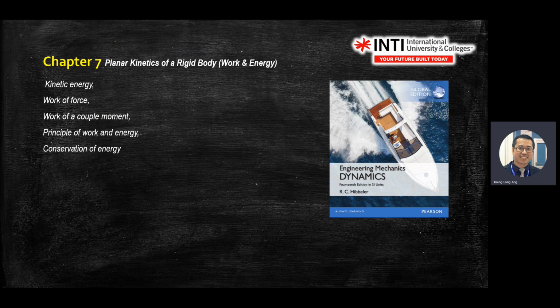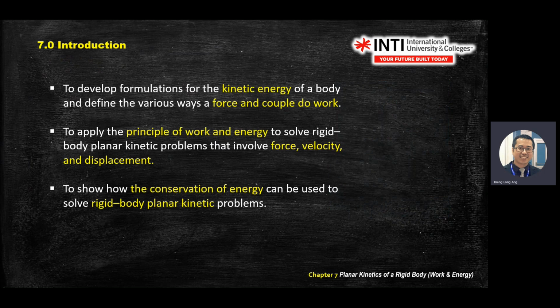Force times the displacement parallel to it gives work, but a moment also does work when you rotate through a certain angle, because this angle is parallel to the motion of the moment. So moment times the change of angle, you get work.